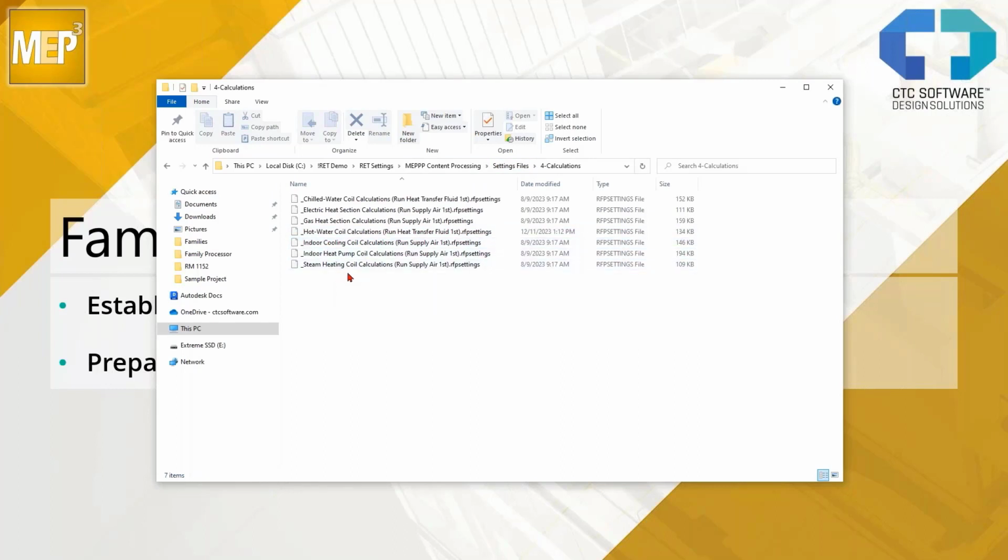And the user guide highlights and points out which settings need to be run and when, right? So I believe it was page 83 where the properties settings and the calculation settings files were listed, and it tells you, run these if you have certain connectors in your families. Then there's another one that says run these if you need to do a certain thing. However, you must run one of the property ones first. So it kind of tells you how to get that going. And I'm going to walk you through it today. So this is how I want to work, and I've organized my settings as such.